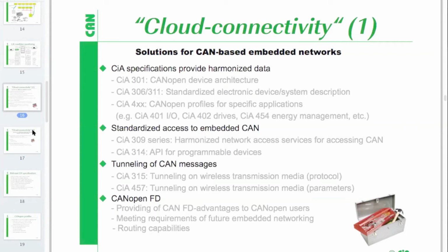This is necessary to know which data I need to use. And we also have so-called device profiles, like encoders and various sensor kinds, and there is already a standardized CANopen interface provided for them. So if you need to implement this in your gateway or your IoT-based solution, this data is already here and you can obtain it.